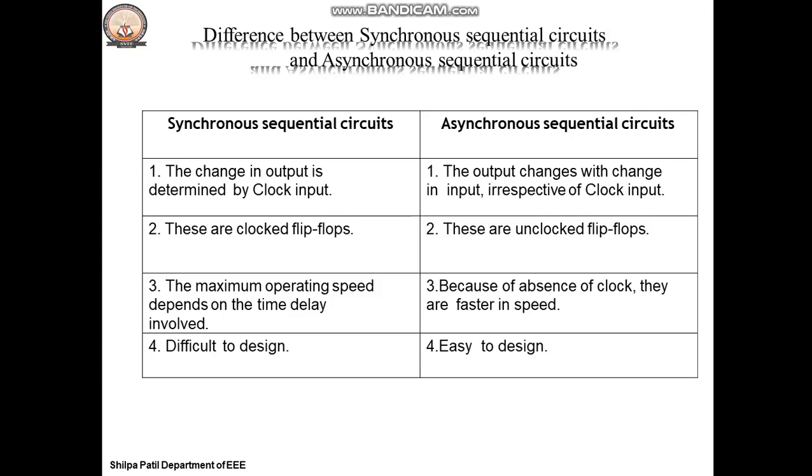The first comparison is nothing but the definition of synchronous and asynchronous circuits itself. In a synchronous circuit, the change in an output is determined by the clock input, whereas in an asynchronous circuit, the output changes with a change in an input, irrespective of the clock input. In a synchronous sequential circuit, the flip-flops are clocked flip-flops, whereas in an asynchronous one, those are unclocked flip-flops.